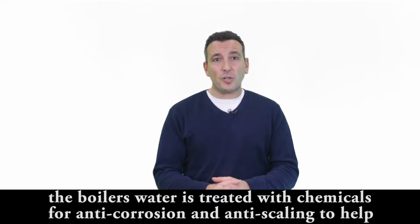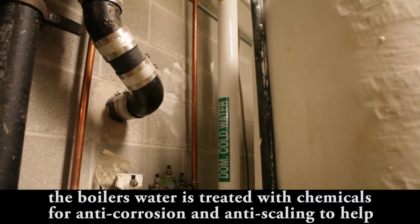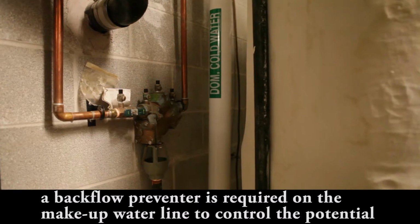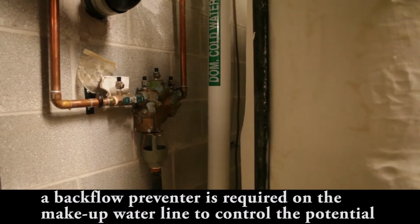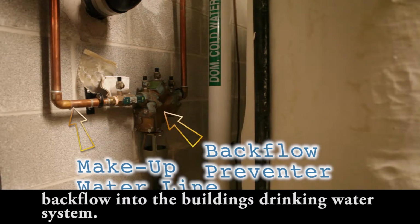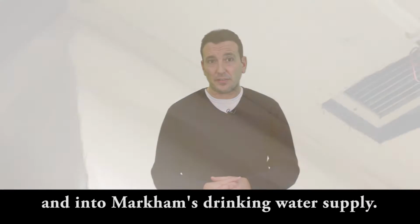The boiler's water is treated with chemicals for anti-corrosion and anti-scaling to help prevent the rust and deposits that may form over time. A backflow preventer is required on the makeup water line to control the potential backflow into the building's drinking water system and into Markham's drinking water supply.